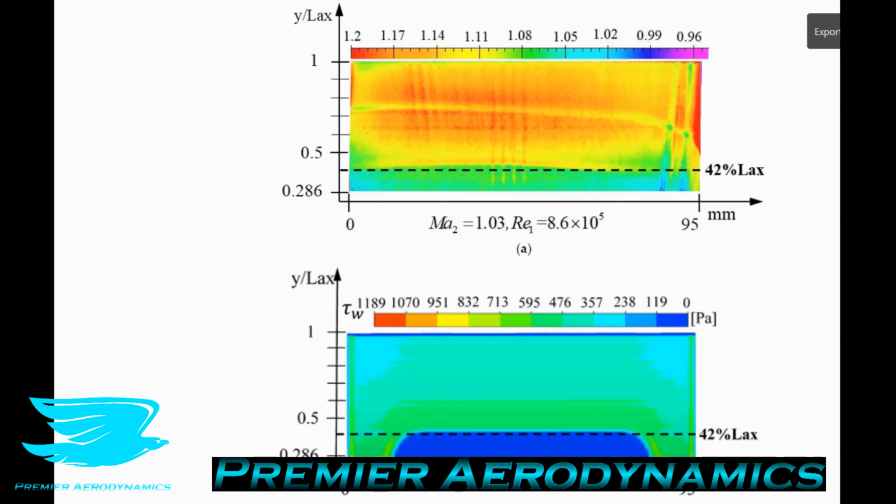9a has some variation in the thickness of the temperature-sensitive paint, as well as potentially the number of luminescent molecules in certain areas, but also maybe surface roughness, etc. So there will be some differences in the illumination, whereas in figure 9b, the intensity is going to be very independent of these parameters because they're not actually taken into account in CFD. CFD is much more uniform. In experiments, we do have these variations for temperature-sensitive paint. However, despite these slight differences, the general overall results are very similar.